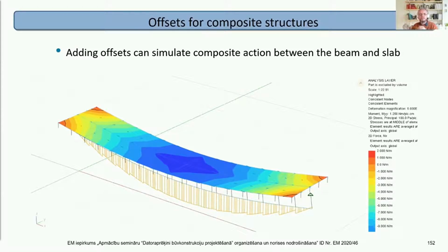For an ultimate limit state model, where you assume that the slab cracks and carries compression only and has zero continuity with the adjacent bays, this is harder to model. And you may start to get tension in the slab. In fact, you can see there are some tension forces being reported in this model, and it's just a single span.